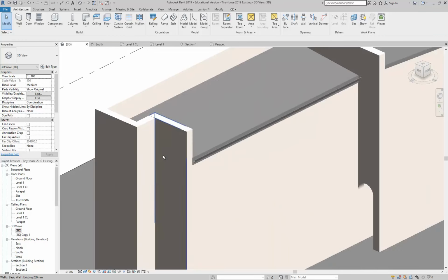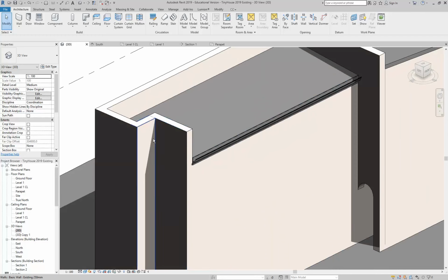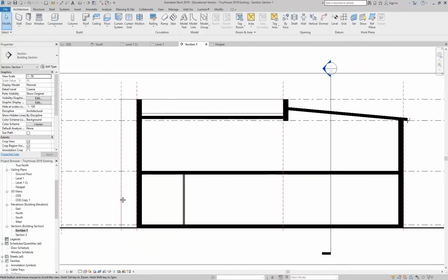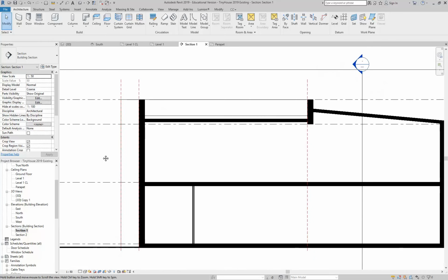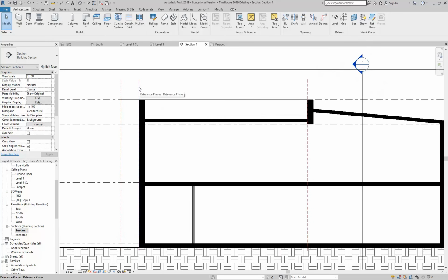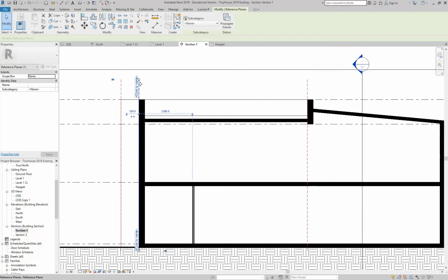And so now we want to make this little projecting gable roof form which sits on the face of this wall here. So that's a parapet wall, and if you know Revit, you'd probably know that you can just pick the surface of that wall to draw on, but at first it's going to be much easier for you, and even later when you know how to do all the different tricks, it's still useful to be able to draw on a plane that you've created, on a reference plane.